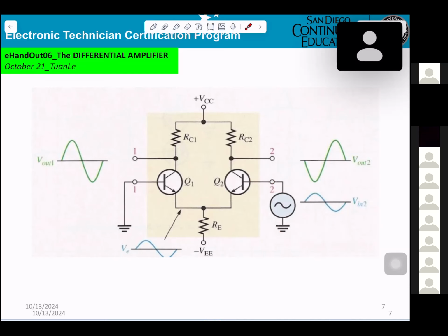Okay, the first thing you can recognize, Q2, when you apply input into the base, output at the collector, so they will be a CE amplifier. Okay? CE amplifier, input positive, output negative. Input negative, output positive. Okay? And you understand you get a sine wave.